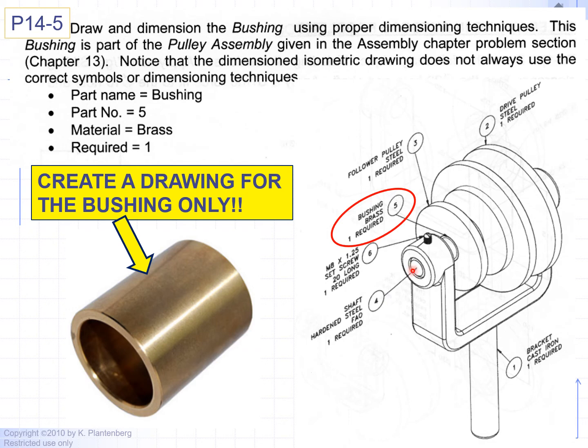Now in this case, they didn't put a bushing, they just put a rod inside, and we have a little set screw that holds the rod. You turn the set screw, it's just a screw without a head. You turn it, and it's just so you can lock the shaft in place. And again, another option to protect this hole, or if it ever gets worn out, you can always drill a larger hole and come in with this press fit bushing, which can always be later replaced if the hole ever gets worn out. You just tap the bushing out and place a new one.